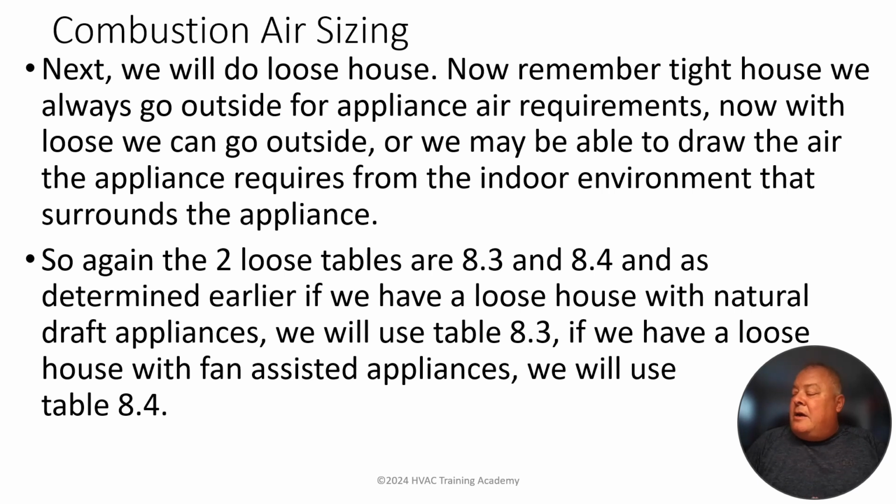So it was pretty easy when it came to combustion air sizing on a tight house. All you had to do, because you knew you were going outside, was calculate how many BTUs we had in that space, and then look it up on our table to determine how big our duct has to be between the outdoors and the room that the appliances are installed in. Now with the loose house, it's going to be a little more complicated.